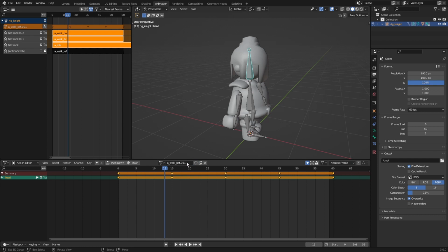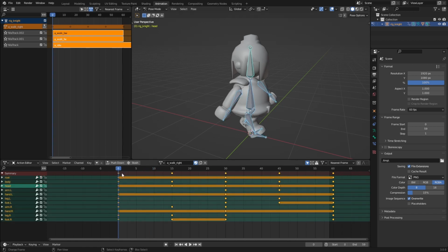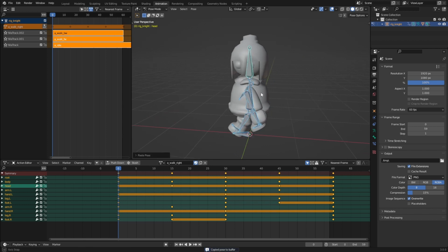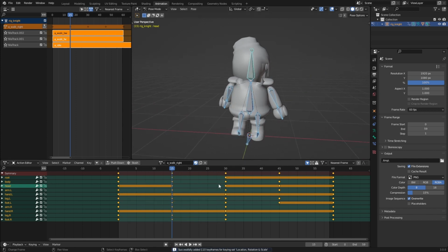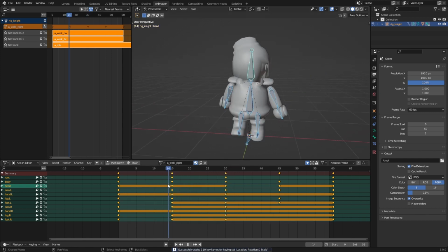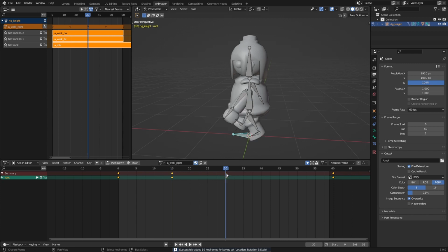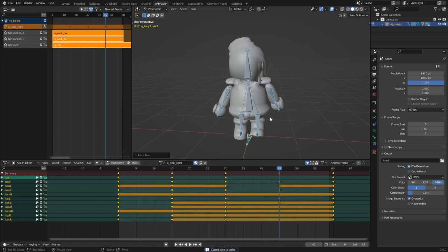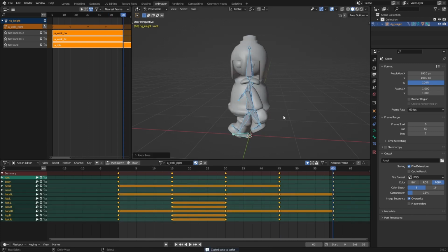If you want the right animation, duplicate it, name it right, save it, delete the one from the stack. And what we can do is go to each one of these 4 sections, take the pose, copy, Control-Shift-V, press I, copy, Control-Shift-V, I, copy, Control-Shift-V, I. And this one didn't really work because we copied the root bone. So we can just R Z -90 on the root bone, press I, and do the same thing here. Copy, Control-Shift-V, I, rotate around Z -90, I, and then A, copy, Control-Shift-V, I.